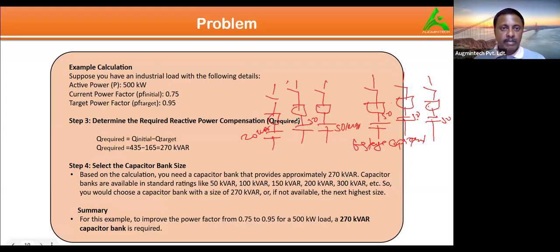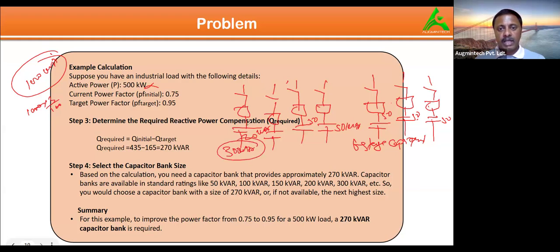And finally, along with this capacitor bank, what you have to install is as per the transformer load. Don't check this value, just check the total transformer capacity, maybe 1000 kVA. Because this load itself is 500 kilowatts, the minimum size of your transformer would be around 1000. So take 3% of this 1000, 3 by 100, which is 30 kVAR. This 30 kVAR would be your direct capacitor. So this is a 6 stage, 1, 2, 3, 4, 5, 6, along with a direct capacitor of around 30 kVAR. This is how you can design the capacitor banks in the future.